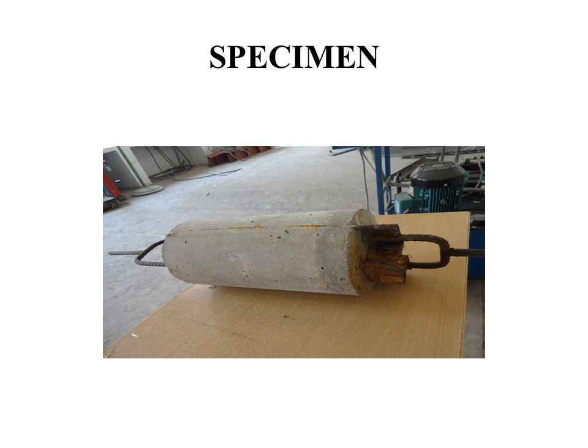This is the actual specimen for experimental method. It is clear from the photo that the steel plate is placed in the center of the cylinder. On the bottom portion, the steel rod is packed by using Resifix G chemical, that is lock fixing chemical. The top and bottom portions were pulled away by using a universal testing machine for this testing.